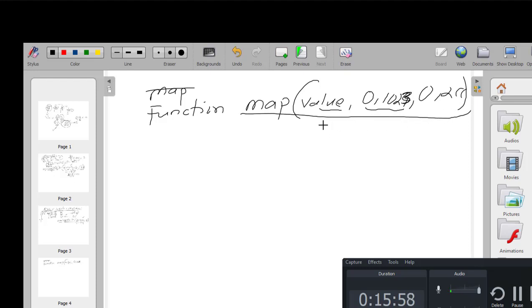Even if I read the digital value from A0 using a potentiometer, and this value lies between 0 and 1023, because we know there are 1024 steps, and between 0 and 255 there are 256 steps, this value can be translated into a value between 0 and 255.